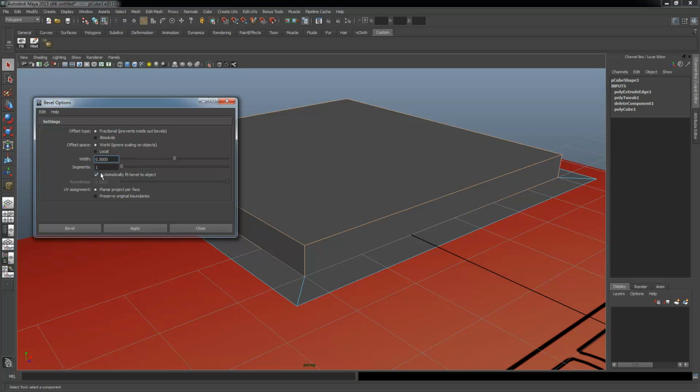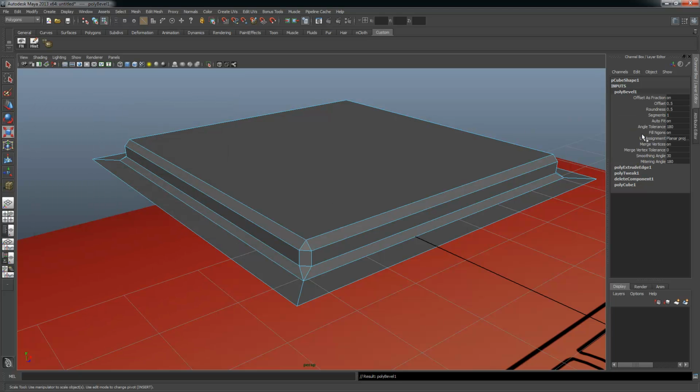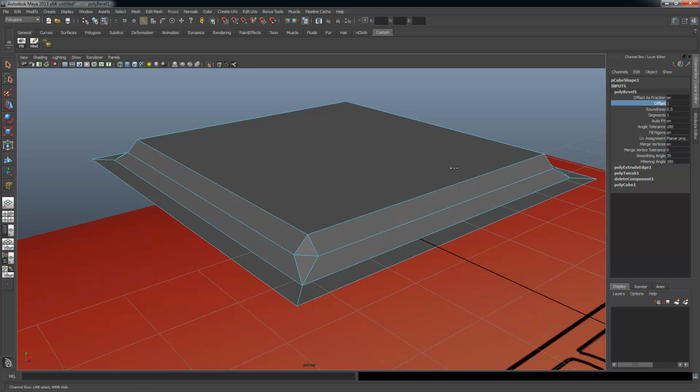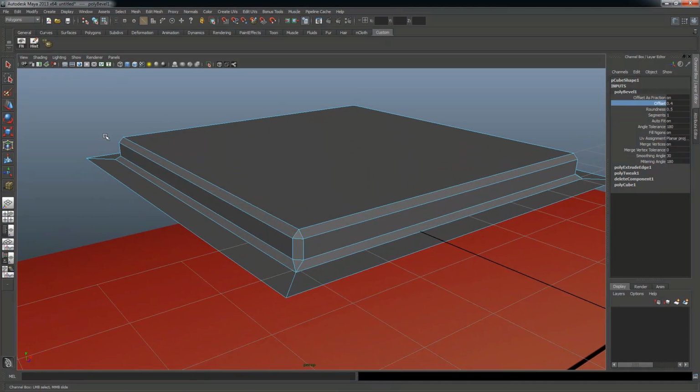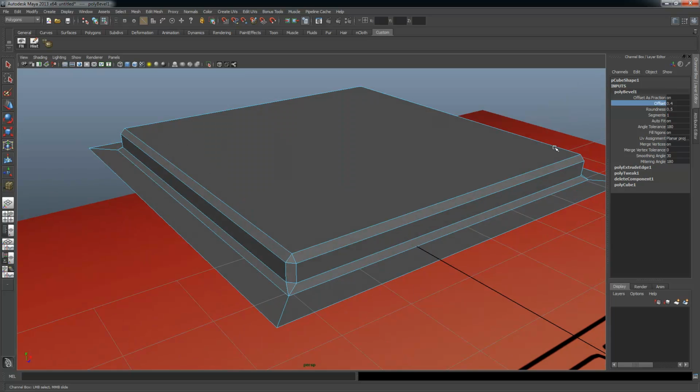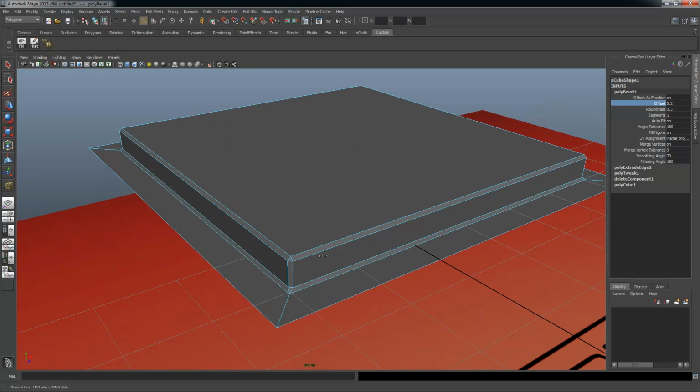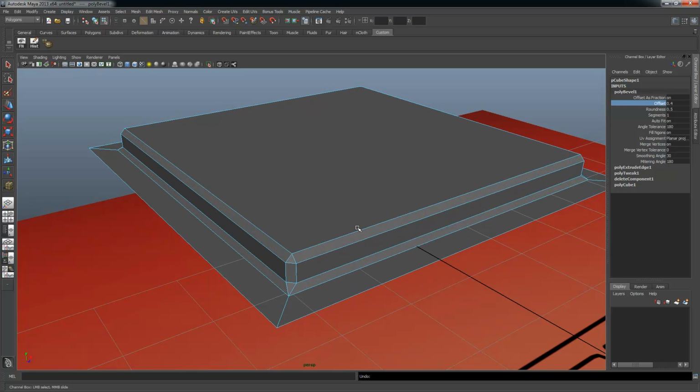There's one setting here that can be a little bit annoying, and it's this button right here, fractional prevents inside out bevels. So I'm going to say apply. It attempts to stop the bevel before it gets to the point where it can go inside out. On this example it's not quite clear what happens, but if you have something that's a compound shape and you add a bevel to it and you get stuck and can't dial it any farther than you want, it's because of that setting.